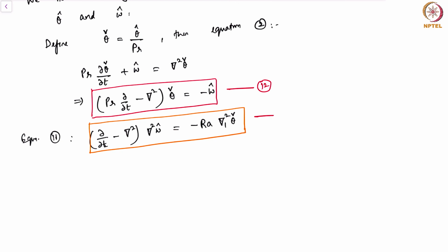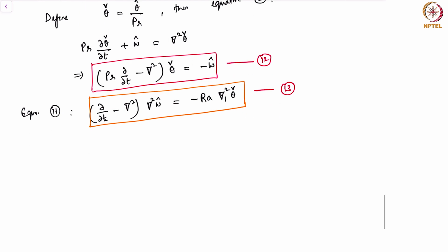This is equation 13, right? This quantity Ra is called the Rayleigh number. As you can see, this is nothing but Grashof by Prandtl number. So we still have only two parameters. So either you can use the Rayleigh number or the Grashof number. Again, the Rayleigh number also would involve the thermal diffusivity in the denominator.